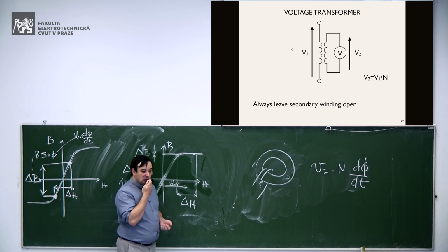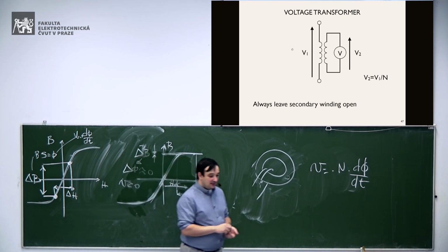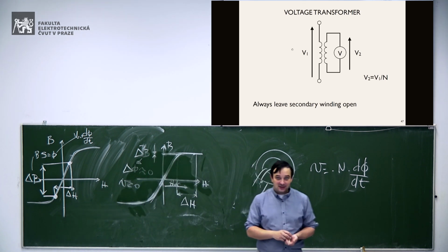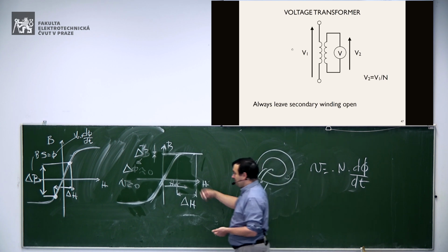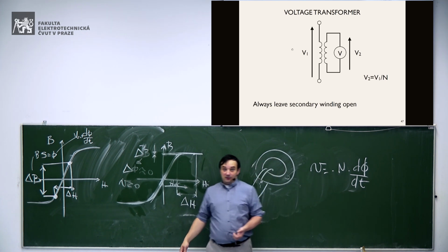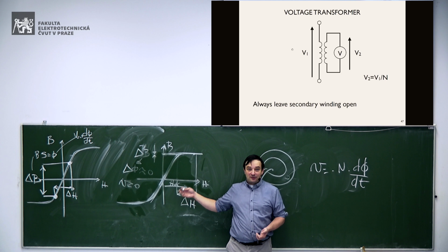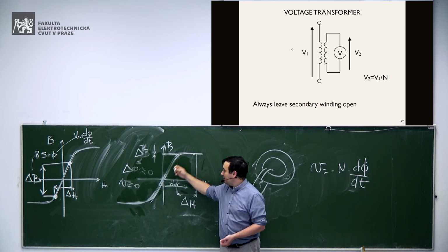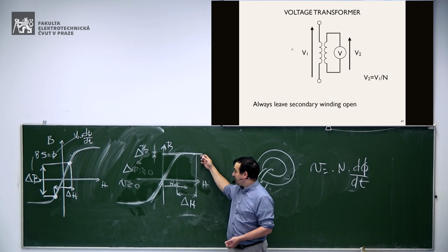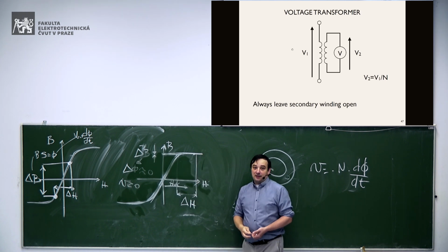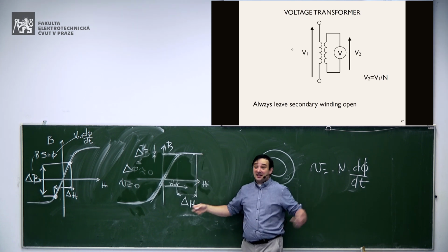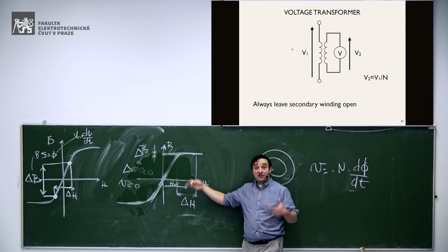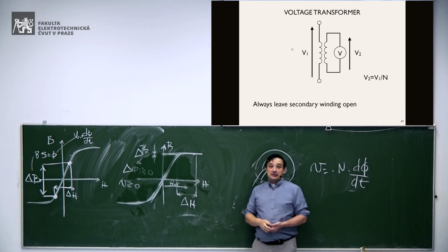Of course, those who design these electric meters are not idiots. They know that people want to try this method. So they, of course, try different methods to avoid this problem. They design cores which have, for instance, saturation at a much larger field. So you will need a very, very large DC field in order to bring the core into saturation. They will,